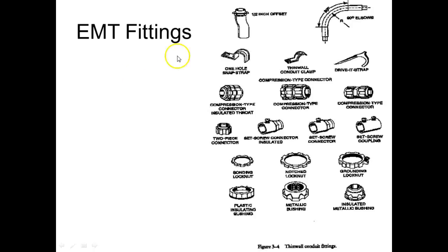So here's some of the EMT fittings. So you've got to support EMT. You understand that, because it's not designed. The only purpose of the EMT is for protection. So you've got to support it. And so you can look over there at our example, and you see they've got to have those supports every so far. And that's in the NEC code book, how far you have to space those straps.